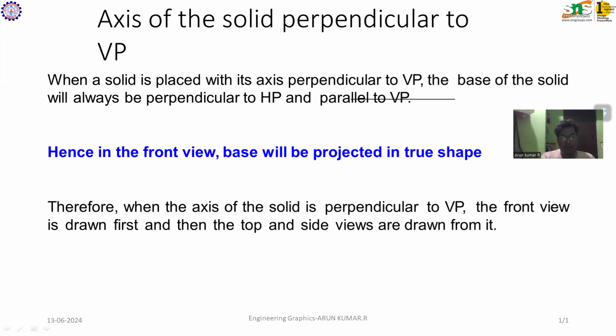you proceed to the front view, and the base will be projected in its true shape. Therefore, when the axis of the solid is perpendicular to VP, the front view is drawn first, and then the top and side views are drawn from it. So let's see.